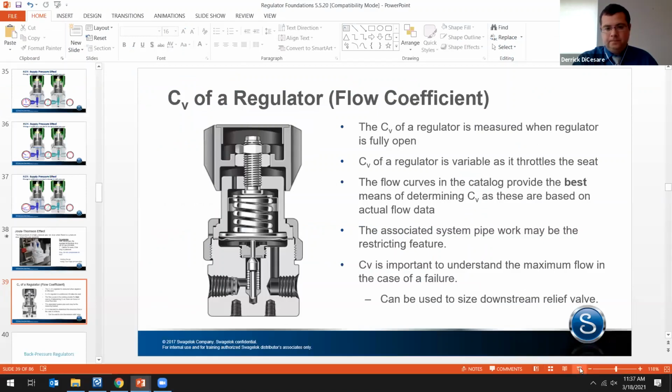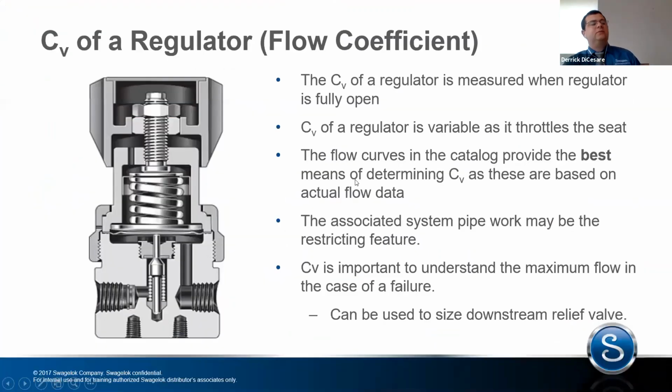All right. So back to regulators. Don't size them off of flow coefficient. Use flow curves or other software to make sure that these are appropriate. The CV is important, but that's not how you size them.